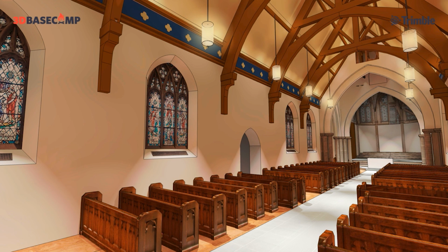So the first rendering here is all from the SketchUp model, and it's a little dark on screen, that's okay though. I'm using Match Photo to create some of the pews, but also using the CAD file to create all the existing space. The pendants right now are higher than they are here, so I think we lowered them a little bit, but all it is is a circle, a cylinder pushed down, made to sort of glow. That way, in this early phase, the client had a good idea of that rhythm we were trying to create between every hammer beam.